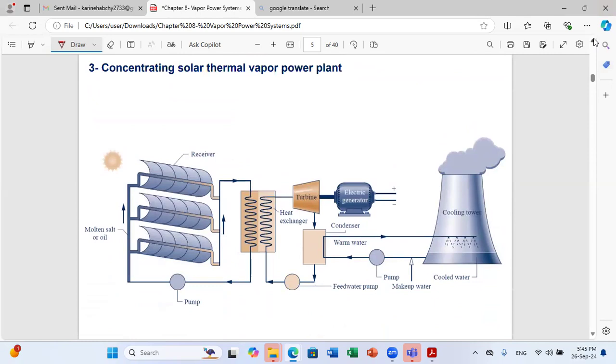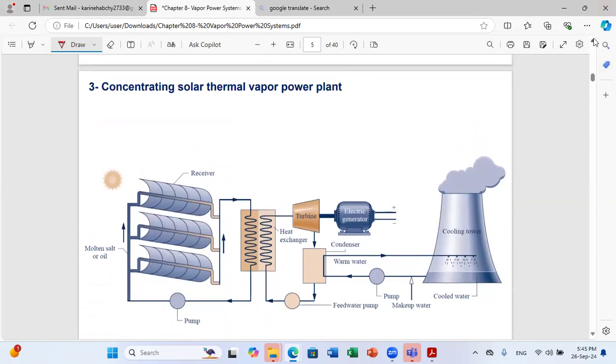Another possible source, as we discussed, is solar systems. You can use concentrating solar systems. You can use PV panels. So it depends, as we discussed a little bit, on the range of temperatures you need to reach; you can select the appropriate solar system to use. With a concentrating solar system, you can reach high temperatures, because you have tracking systems that can concentrate the solar energy, and they can reach the high temperatures that you want.